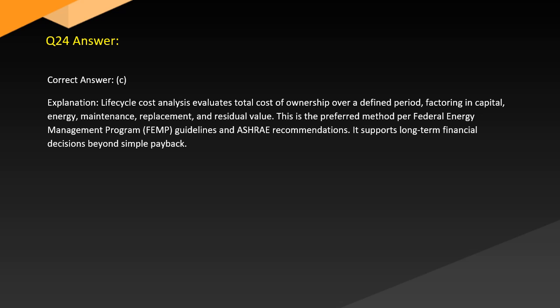Answer. Correct answer: C. Explanation: Life cycle cost analysis evaluates total cost of ownership over a defined period, factoring in capital, energy, maintenance, replacement, and residual value. This is the preferred method per Federal Energy Management Program (FEMP) guidelines and ASHRAE recommendations. It supports long-term financial decisions beyond simple payback.